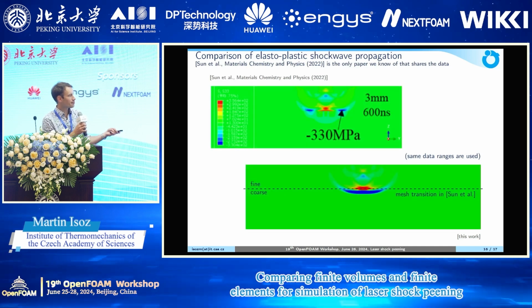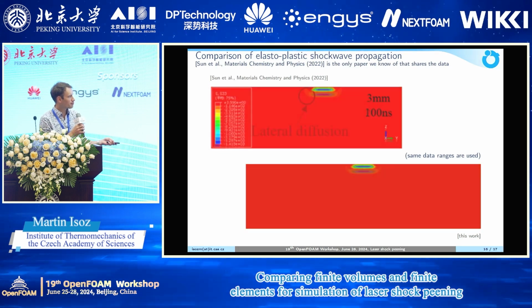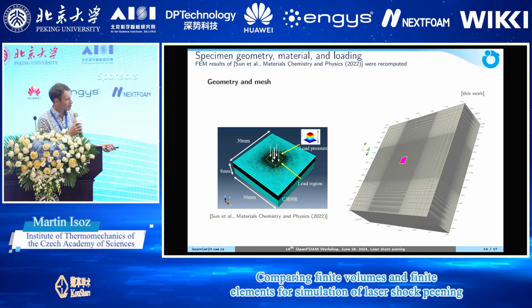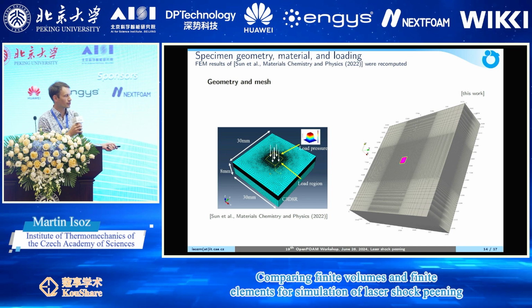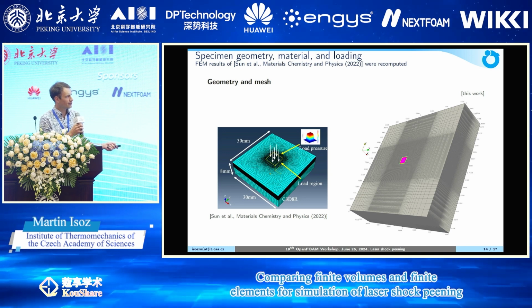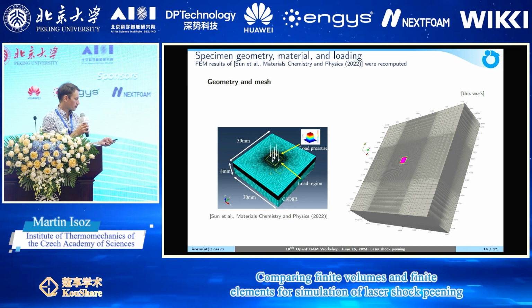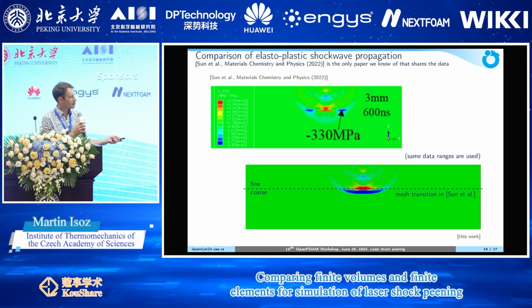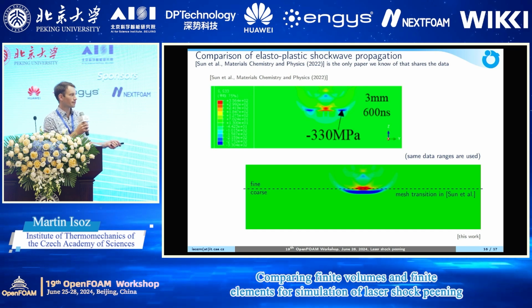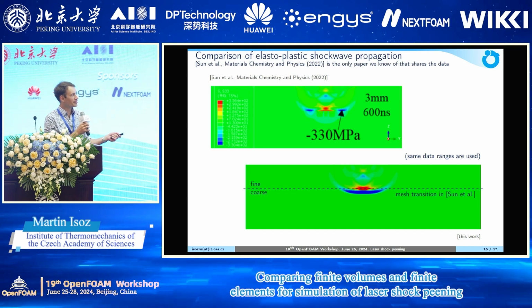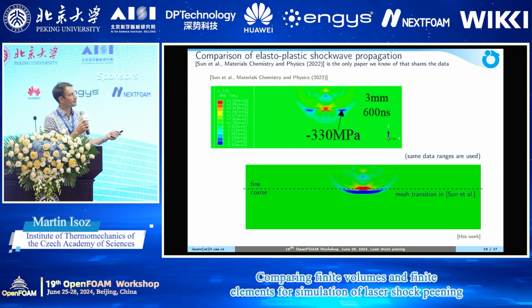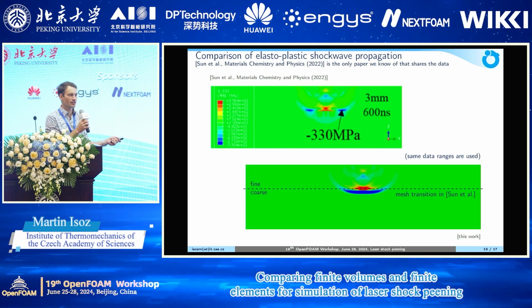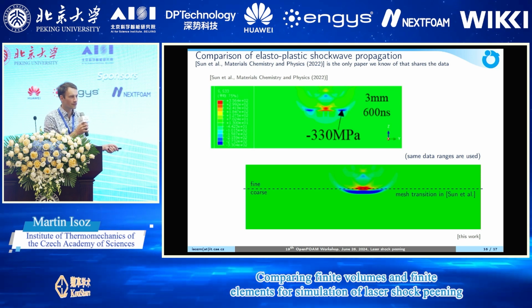Now we see a difference, but if I go a little bit back and show you the meshes, here you can see the transition from a very dense mesh to a coarse mesh. In our simulation we have a smooth transition and a little bit more below. And the difference in the dynamic data happens directly at the transition. So I think that these results are actually filtered by the mesh. There is some refracted wave because of the interface in the mesh, and this energy is filtered out, which is the cause of the difference in here.